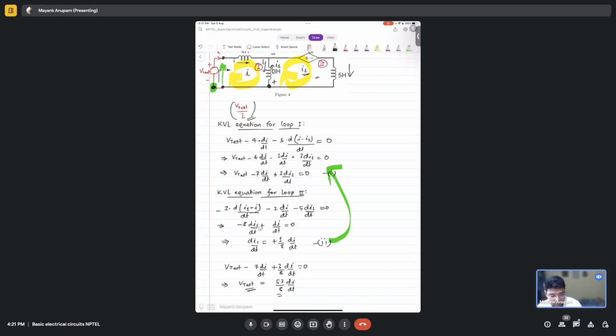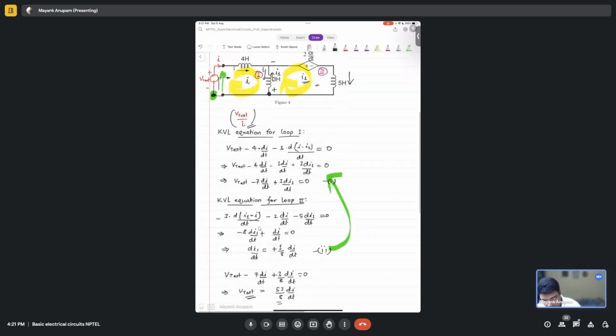So understand what I'm asking, everyone. One of our friends told us that whenever we want to find some equivalent impedance across two terminals, we need to attach a voltage source, find out the current, and then take their ratio, right?